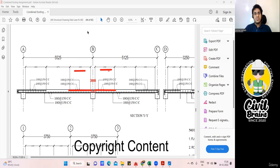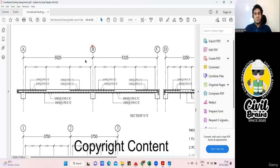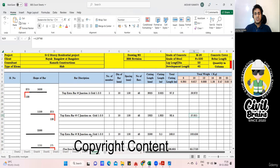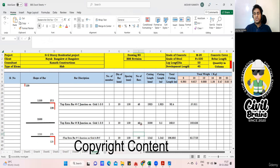The straight length you are going to get. Okay, that's it. If you do that, you'll get the cutting length of that. We'll go back to the Excel sheet. I've written it here. Top extra bar at B junction. This is my B junction. Okay, great. So top extra bar at B junction on grid again 1, 2, 3. So this will be how much? See, 1650 plus 300 is the width of your beam plus 1550 is on the right side. Finish. Number of bar I told it remains the same. 48 only we are getting. Cutting length will be directly 3500.